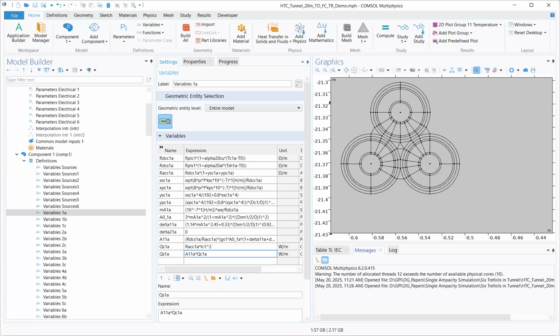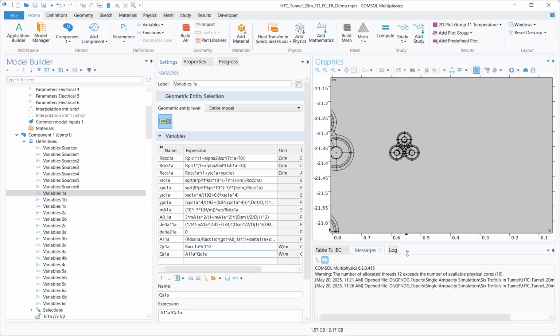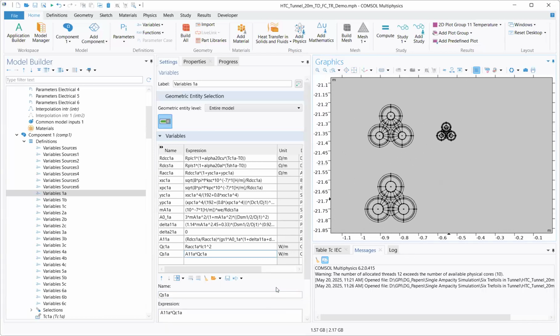So when David has here 6 cables, the electromagnetic fields are constrained to the circuit. So only the eddy currents, proximity, and skin effect are considered per circuit. The IEC doesn't have the equations to consider the induced electromagnetic fields from one circuit to another. So you didn't have to solve the electromagnetic problem first. You don't need to solve the electromagnetics if you go this way.